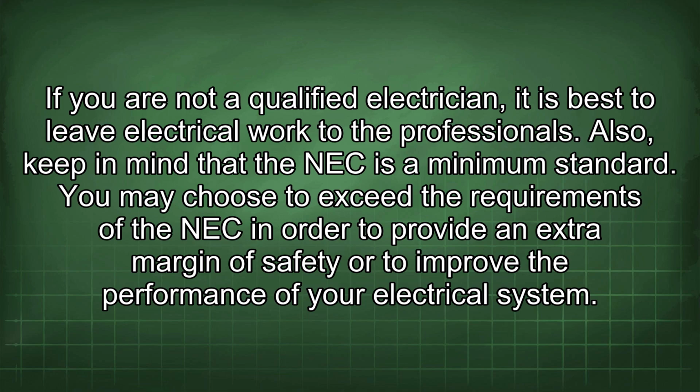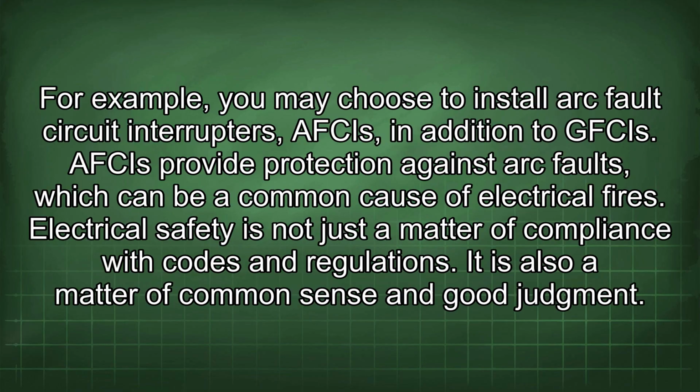Also, keep in mind that the NEC is a minimum standard. You may choose to exceed the requirements of the NEC in order to provide an extra margin of safety or to improve the performance of your electrical system. For example, you may choose to install arc fault circuit interrupters, or AFCIs, in addition to GFCIs. AFCIs provide protection against arc faults, which can be a common cause of electrical fires.